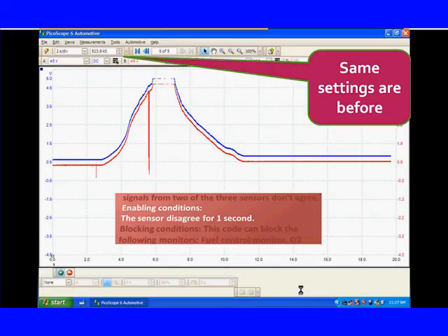But what we can't tolerate is this glitch you see. And actually, we see two of them. One before we open them and one almost open. This causes a major drivability problem. Why? Because the software says, wait a minute, I do not have agreement with the two signals. So it does its plausibility check. But which one of these signals looks plausible? Well, my engine speed has been doing this, and therefore I am going to believe the blue trace and ignore the red trace.